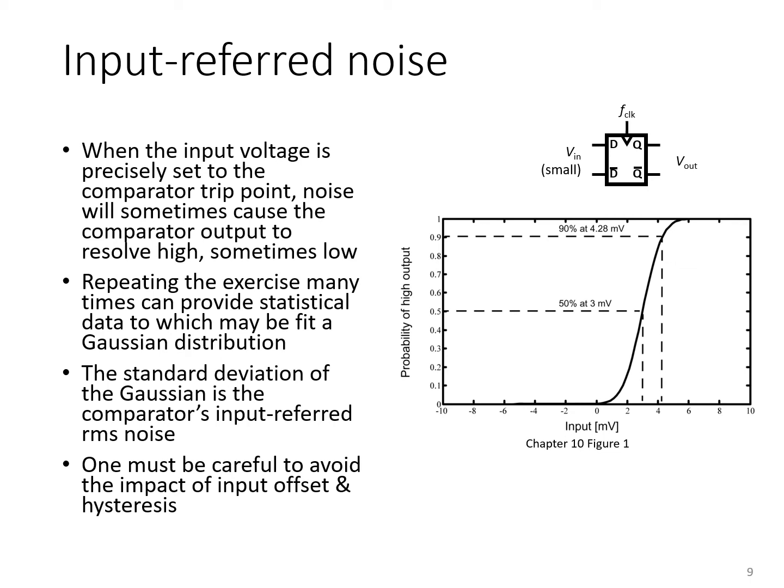So it's difficult to understand what precisely the noise impact of each transistor is. There are lots of good papers on the topic, and they continue to come out, in fact. But we're going to instead just focus our attention on quantifying noise in a comparator and knowing how to measure it in simulation.